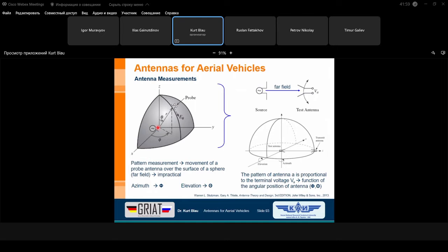For instance, the radius or the distance from the antenna under test has to be held constant at every point. And if you go only, let's say, with a normal handheld measurement system around this area of the antenna, then you can go around in a certain circle. It's no problem. But if you have to go up in the height, then the problems are starting.